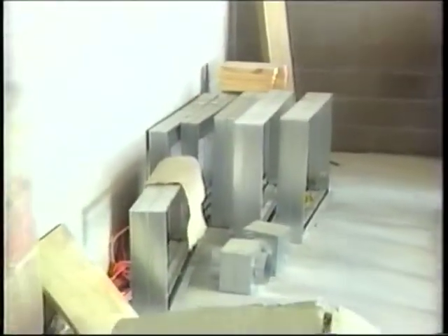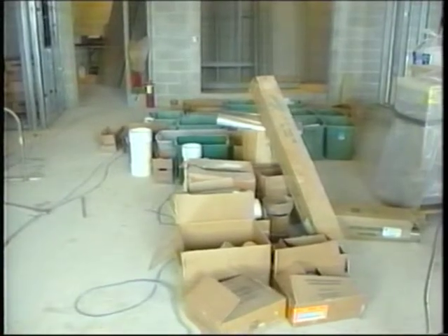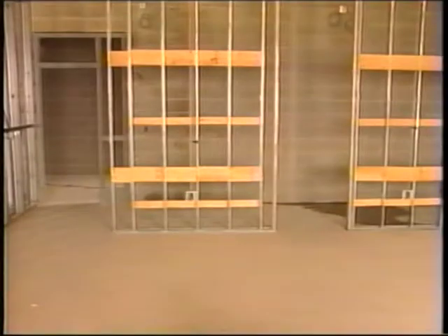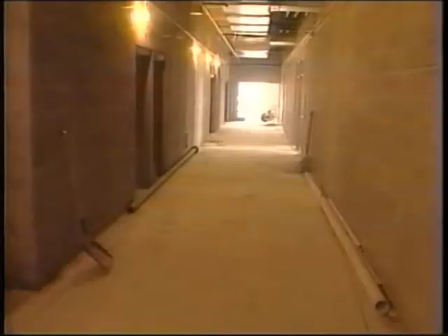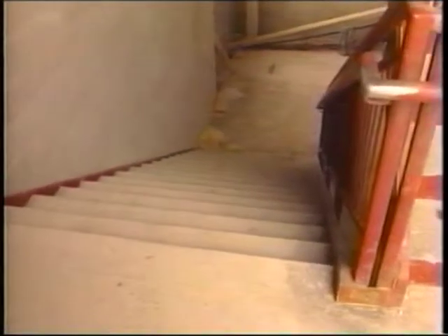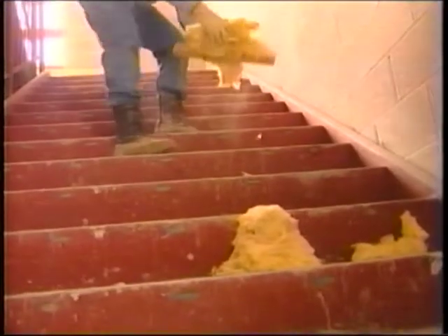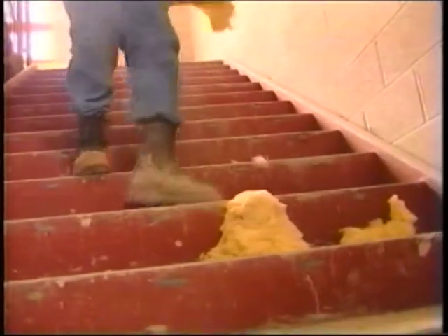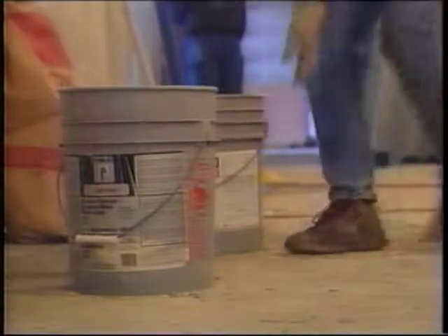Areas like these may look like good places to place debris until it can be properly disposed of. Out of sight, out of mind, right? Not if it can cause accidents. Places like work and storage areas, walkways, passageways, and stairways can become easy dumping grounds. Be sure to keep them clear. Gather debris and remove it on a regular basis throughout the day. Don't let it pile up. This is especially important in the case of combustibles.